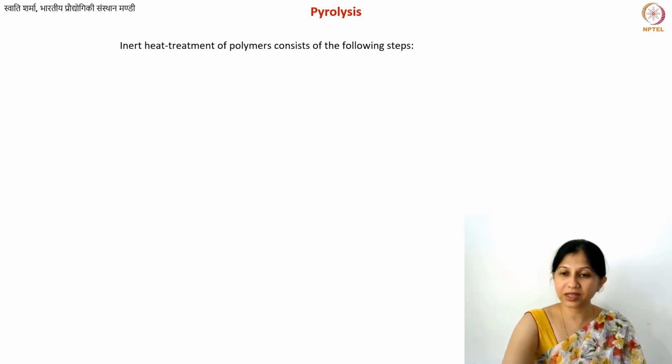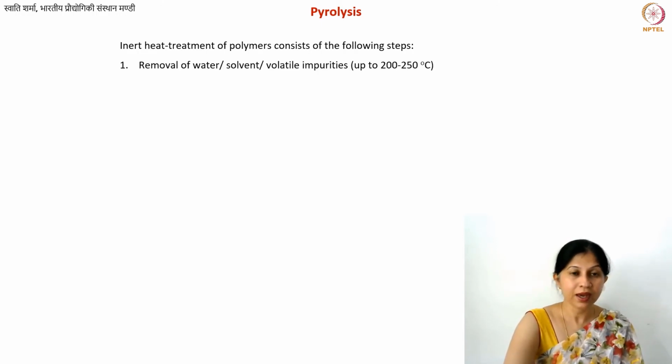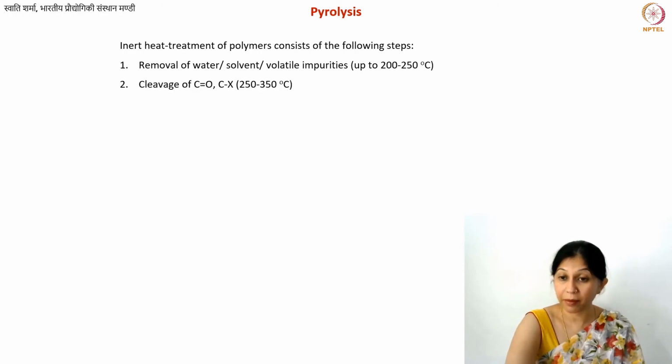So based on all of these things, let's define some very fundamental rules for all the polymers. So not just for PVC. Okay, what happens up to 200 degrees? You have a polymer, you may have some water in it, you may have some very standard volatile impurities. Those things will go away up to, let's say, 200 to 250, and nothing really chemically changed in most cases, depending of course upon the degradation temperature of your polymer.